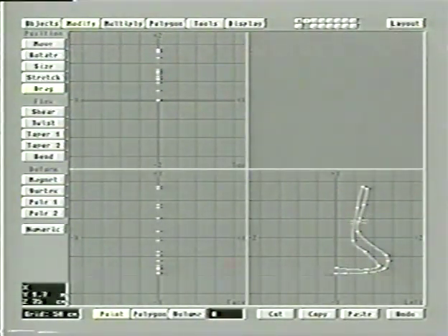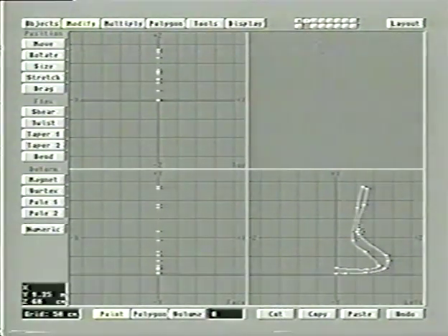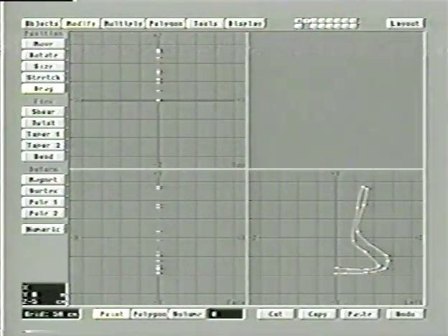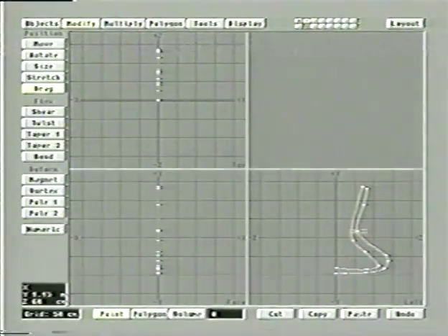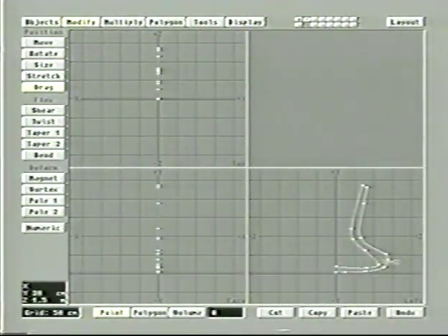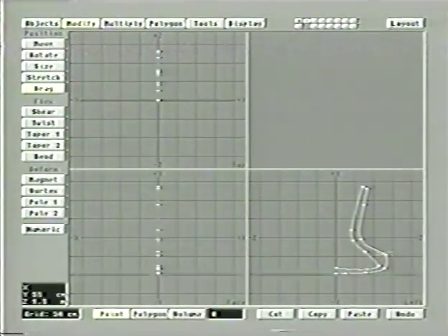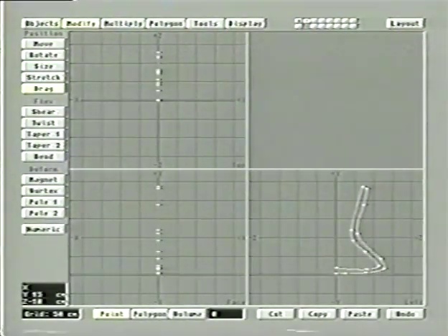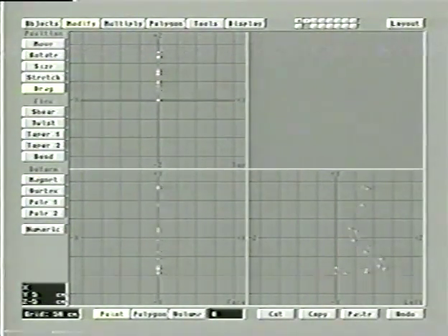By the way, this point here to me is extra. I'm going to go and select the point and cut it because I don't feel I need that point there really to do the shape I'm trying to do. So since it's extraneous, I'll just get rid of it. Go in. Now, one thing is, you notice these are curves here. Got another point I want to get rid of here. Cut. These are actual curves, but when it lathes them, when it brings them around in 3 dimensions, they are turned into polygons. And do one thing up here. Close enough for a videotape right now. Let me just leave it like this.